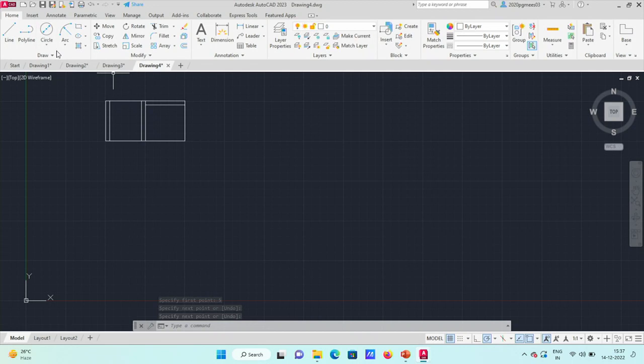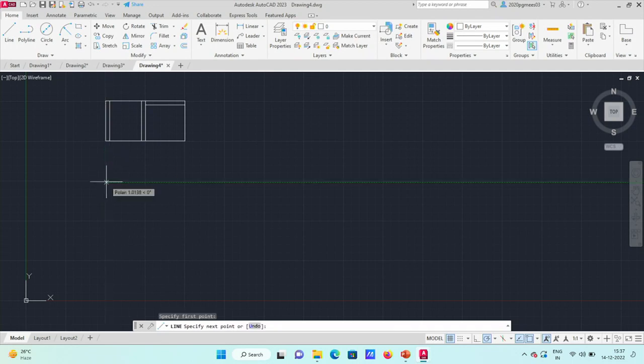Next, since we have the circle, this will be visible in the front view. First let me draw the front view, after that we will draw the chain dotted line according to the circle one. So, project it down, the height will be 50, next we have 100.